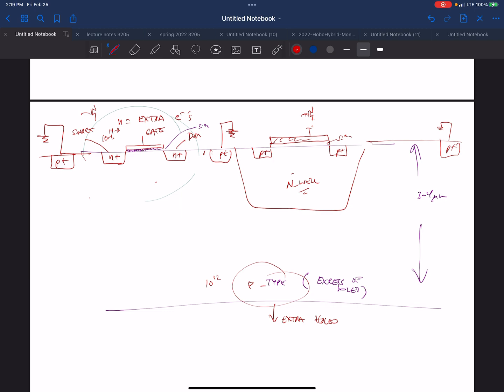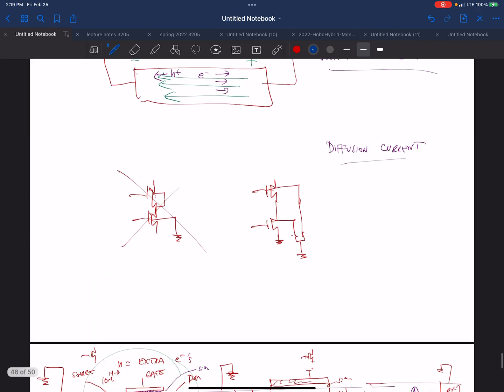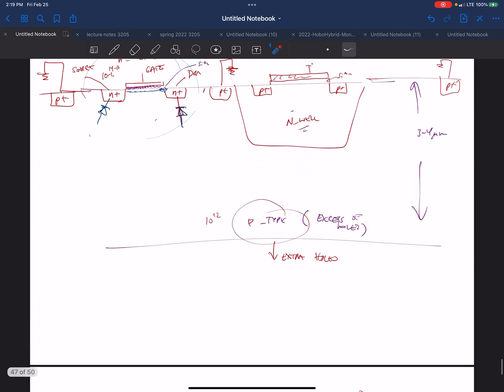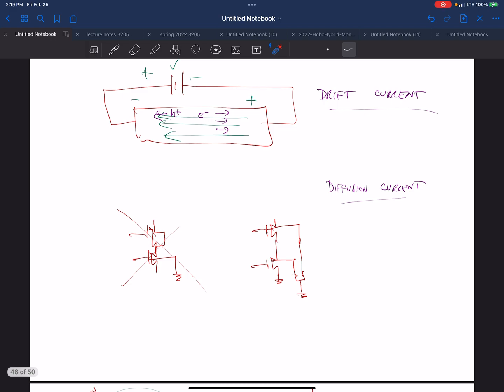Remember, this is a junction. It's a diode here. Okay? If this guy was inverted, it would be a short this way, but it's always a reverse bias diode to the substrate. Okay? And same with this one. Meaning that this is allowed. Okay, I can have some voltage on my drain and source different than my substrate or ground connection. But the substrate NMOS connection is always connected to the substrate. With me? Okay.